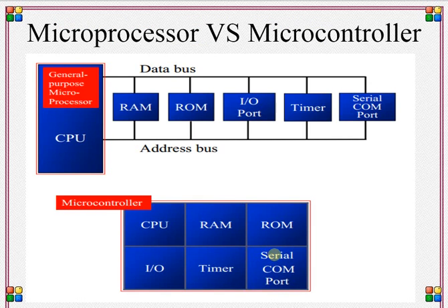Now, comparing the microprocessor and the microcontroller, a microprocessor must add the RAM, ROM, IO ports, and timers externally to make them functional, and this makes the system much bulkier as well as expensive. It does have its own advantage of versatility in the amount of RAM, ROM, and IO ports. If we talk about the microcontroller, the fixed amount of on-chip RAM, ROM, and number of IO ports makes it ideal for many applications where cost and space are important, which means that typically they differ in terms of where these resources lie, whether they are internal or external.